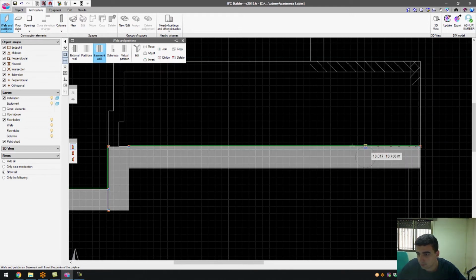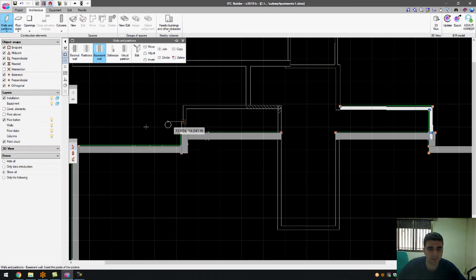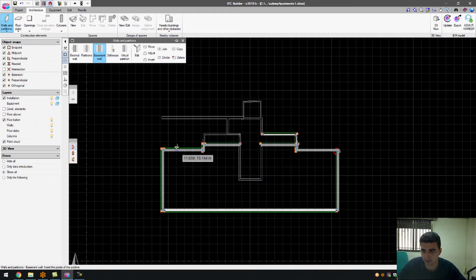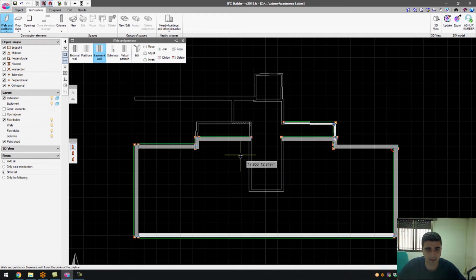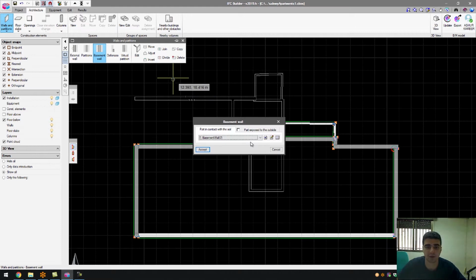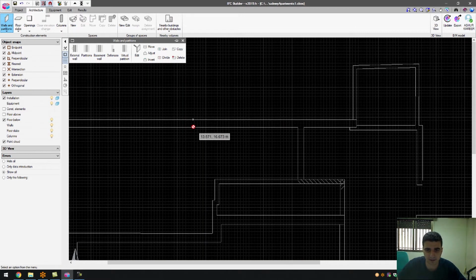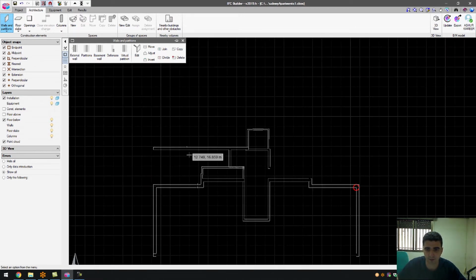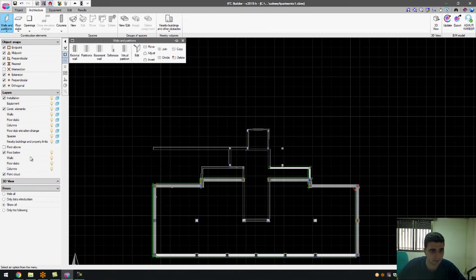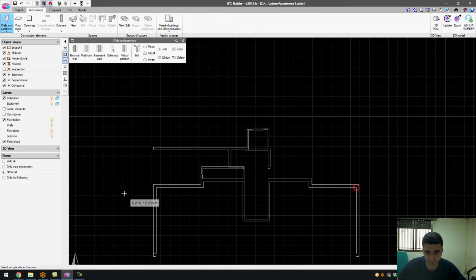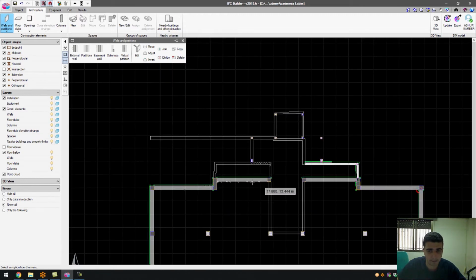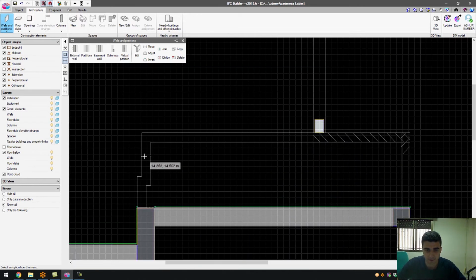Inserting that wall. Cool. Now, so that's our 0.3 meter thickness. Let me just quickly check this one. Was this 0.3? Oh, that's 0.26. Okay, beautiful. Now, turn on the constant elements now. Now let's move on to the next dimension of the wall, 0.15 meters for the basement wall.